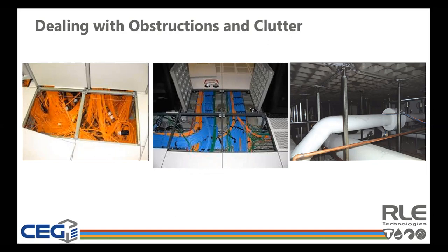Also, limiting chilled water piping to the perimeter of the room and regular cleaning and removal of legacy cabling can all help in maintaining proper cooling throughout the data center. I actually worked with a data center a few years ago in the Minneapolis area that was originally designed with a relatively shallow floor. I think it was about 14 inches deep.